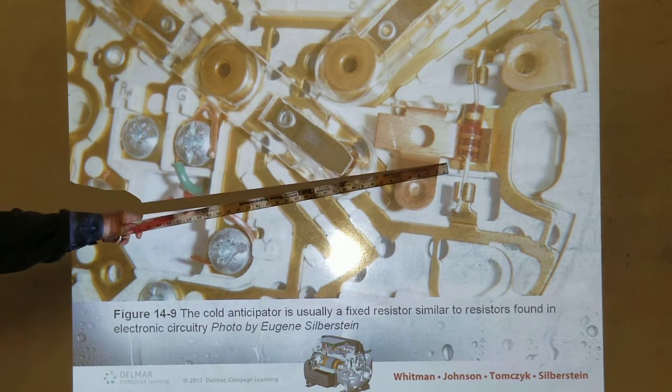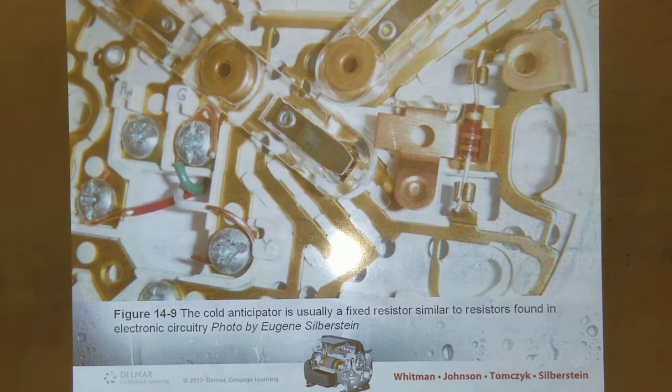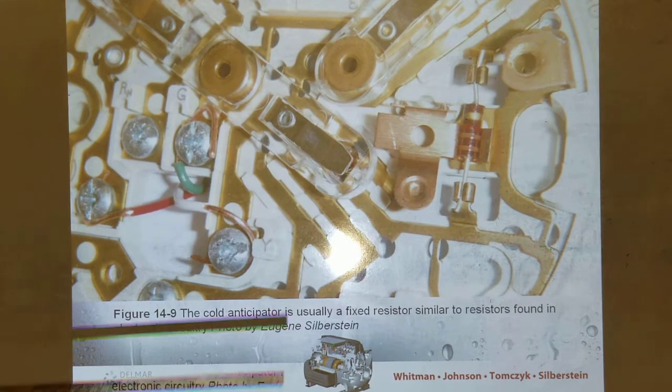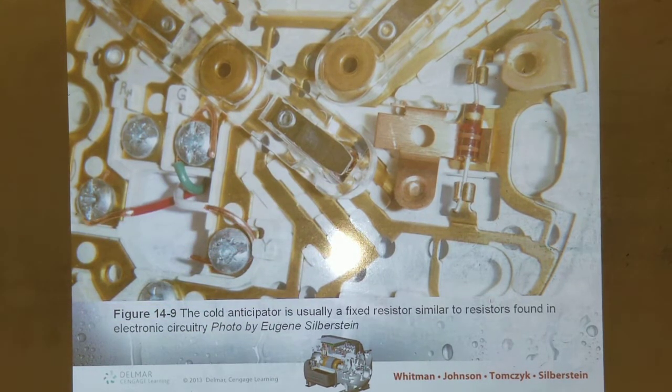How it works is it generates just a little bit of heat. So inside the thermostat, the thermostat thinks that it's actually warmer than it actually is. So it holds the system on longer. Understand how that works? You're just heating up the thermostat a little bit, so the system will stay on.